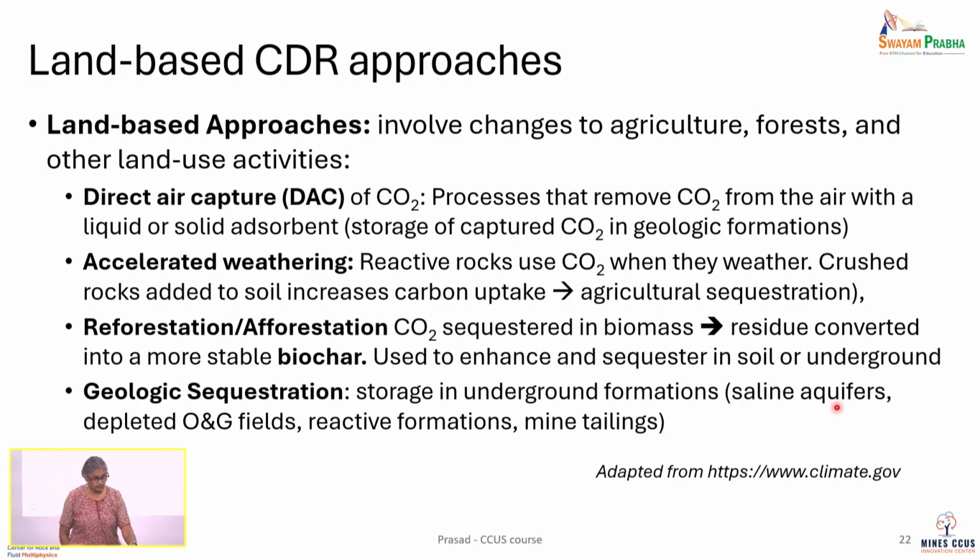In the US, there is a requirement. If you want to use saline aquifers, the salinity needs to be above 10,000 parts per million, so NaCl equivalent. Your typical oceans will come in at around 3,500 parts per million, not 3.5 parts per million. The requirement here is to go to 10,000. Above 10,000, it's not potable.